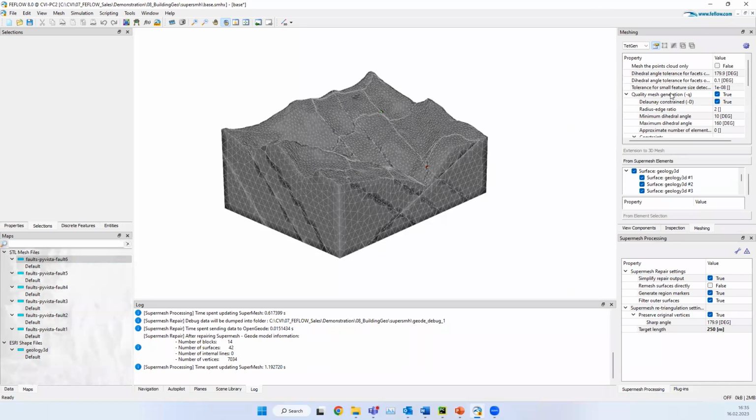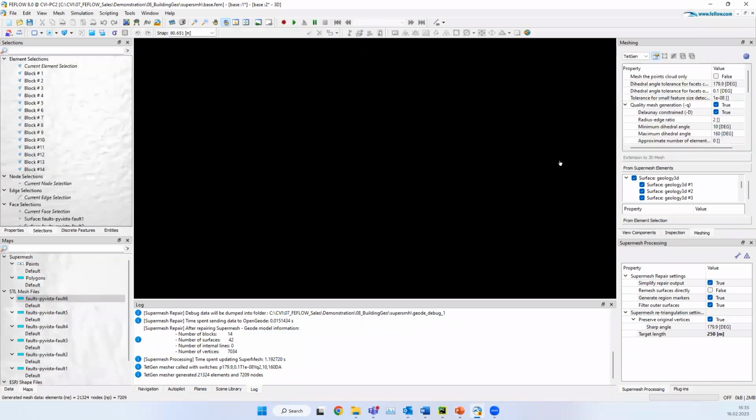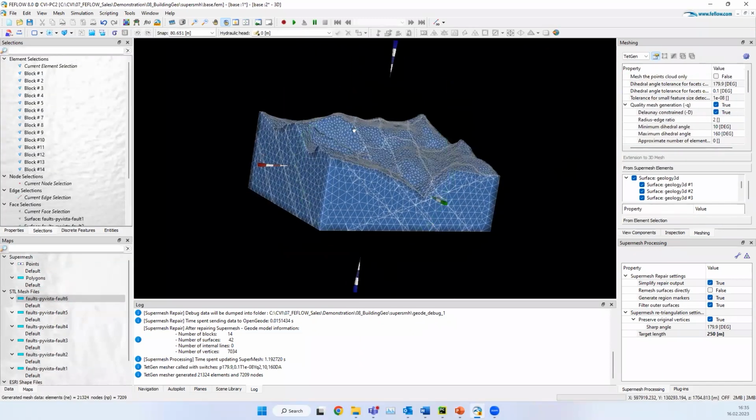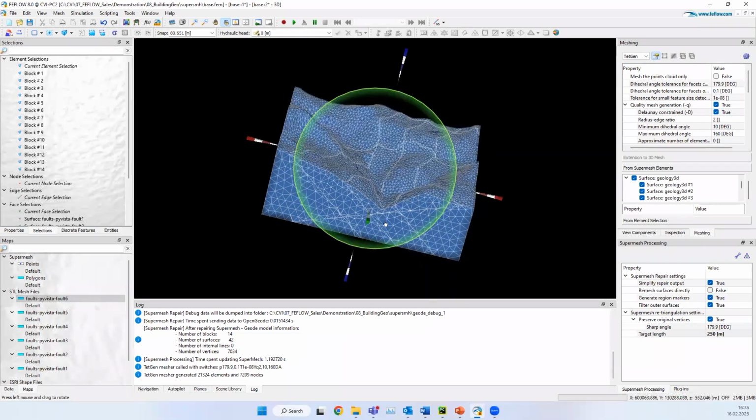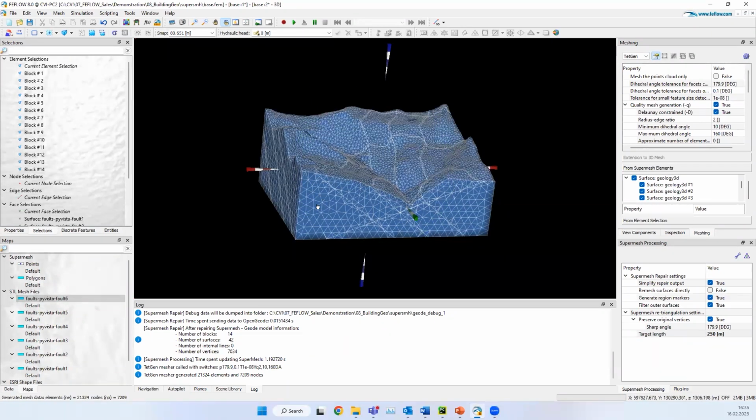For this, you go to the meshing panel, then you have TetGen, and if the triangulated mesh is really good, you can call TetGen with preserve external boundaries and generate the mesh. The mesh is done, and it has the different cuts and intersections. This is doing the minimum because it's not really touching the outer faces of the domain. Here is something you need to be aware of.